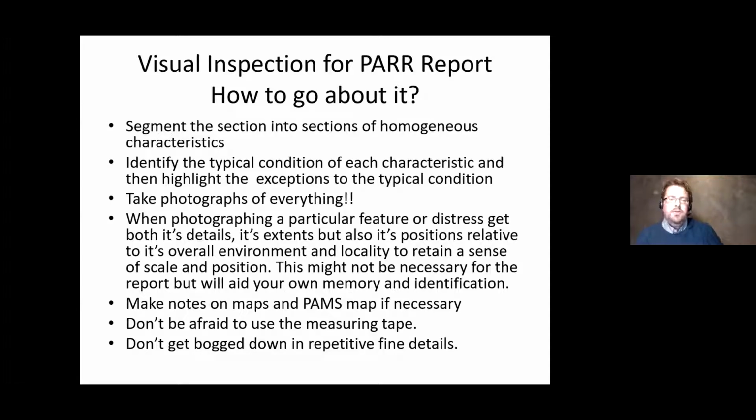It just makes life easier that when you identify what the typical condition of each characteristic is, you can make that note as a typical condition, and then you can focus on those features that are not typical to the condition. It saves you having to go and detail every single feature, every single crack. If the entire section is heavily rutted, heavily cracked, you don't need to mention them all. But if there's a 10-meter section in the middle of an otherwise good road that is heavily cracked, then mention that. Photograph everything. It's just easier when you're there to get the photographs than have to go back out on site.